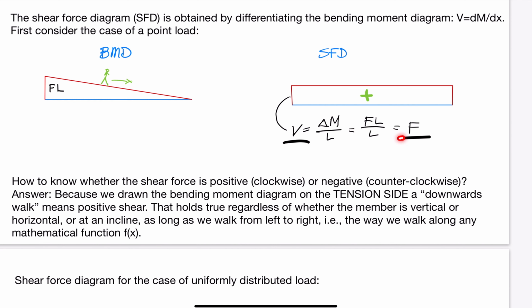The result is F, and that value makes sense, because F is the point force at the tip of the cantilever. However, we need to pay attention to the sign of that shear force. Because of the way the load, F, acts, you may intuitively see that the shear force tries to rotate each segment of the beam clockwise. In the conventions adopted at Terje's Toolbox, clockwise shear force is considered positive.